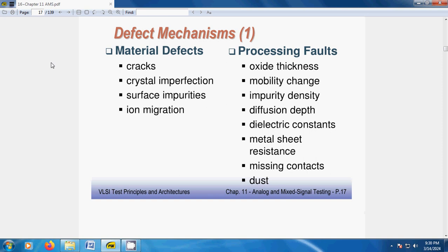For example, when you apply a dielectric layer, such layers are mostly brittle in nature. So even a small thermal stress, for example from an ion implantation or etching process, causes thermal stress in the nearby layers due to different nature of expanding with temperature.